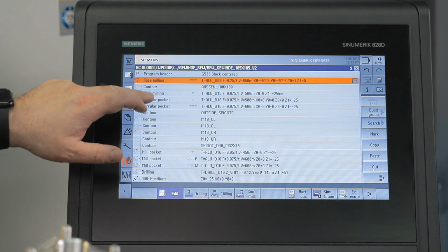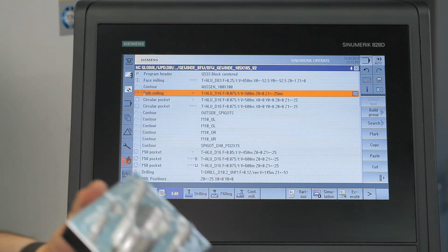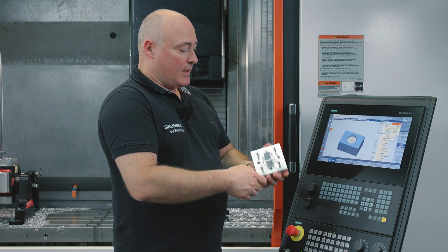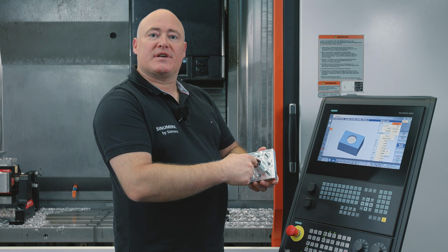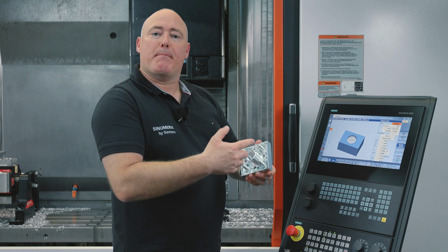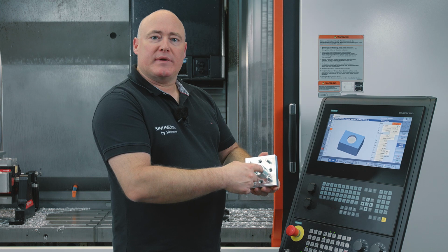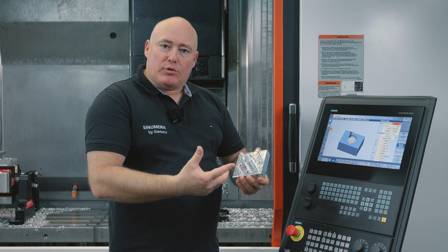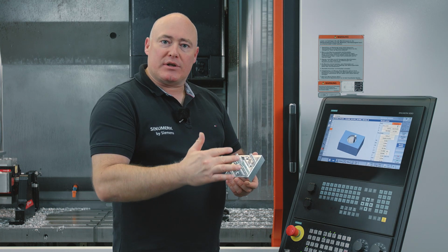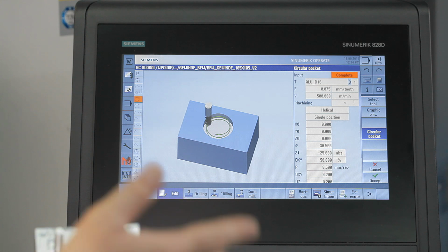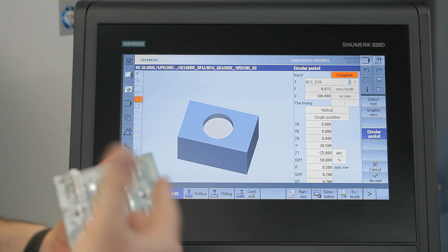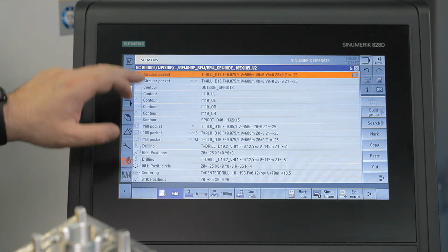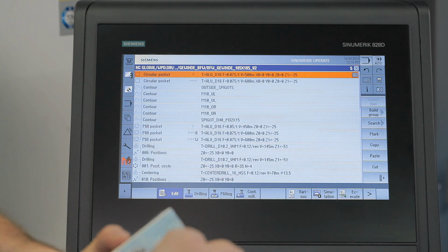Following this, external milling is then performed around the outside to depict the outer contour, and the tap hole diameter is prepared in the next stage for our M32 by 1.5 thread. This diameter totals 30.5 mm. Since the formula for calculating the core diameter is nominal diameter minus pitch, 32 minus 1.5 equals 30.5 mm diameter. Following this step, these contours, which we refer to as islands, are milled.